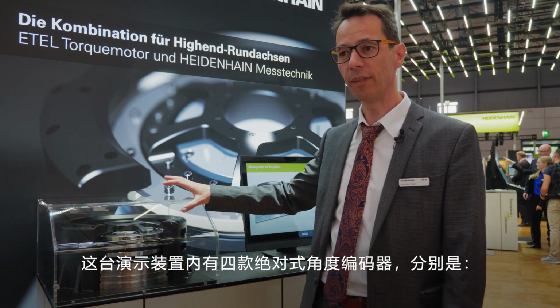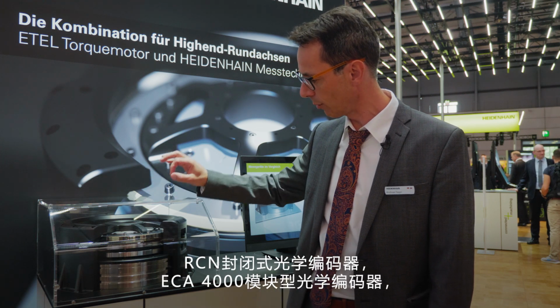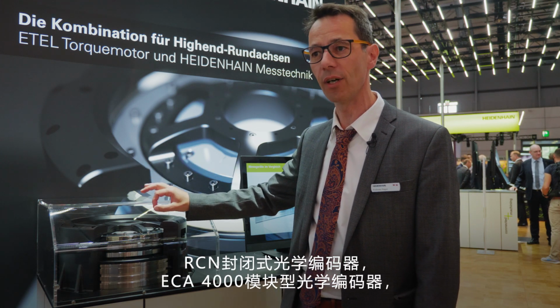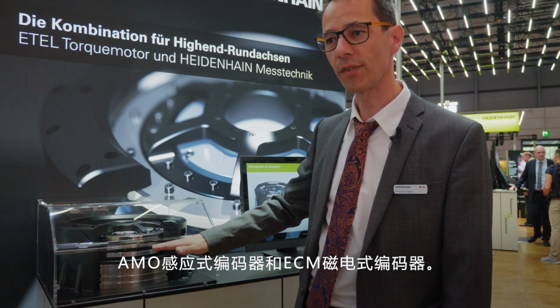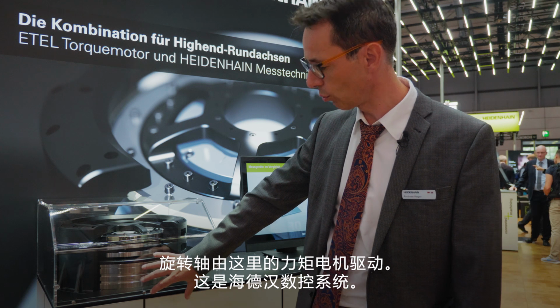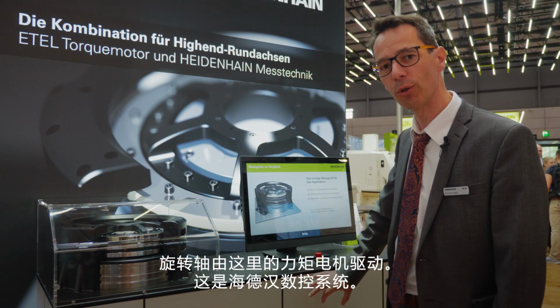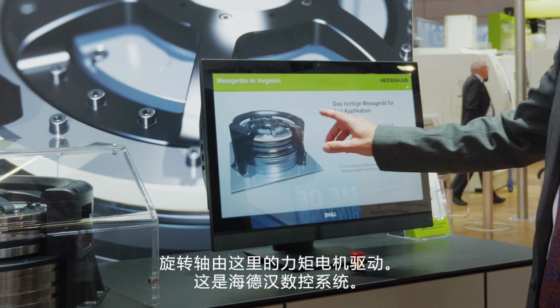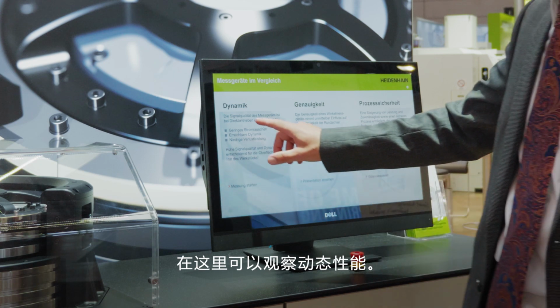4 different absolute angle encoders are installed: a sealed optical RCN encoder, a modular optical ECA 4000 encoder, an inductive AMO encoder, and a magnetic ECM encoder. The axis is driven by a torque motor here. A Heidenhain control is installed here. And the dynamic characteristics can be viewed here.